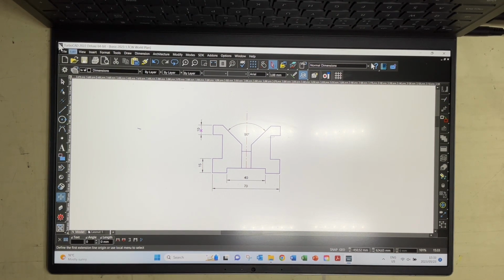From this video, you should have learnt how to draw construction lines using the construction line palette, drawing parallel construction lines. If I've got that, you should have learnt to lock the little offset block and to be able to press tab, highlighting that little block at the bottom there, and then typing in whatever dimension you want in there to offset that construction line.